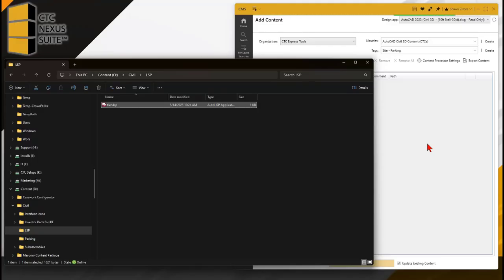So that saves a lot of the heavy lifting that we do with our AutoCAD profiles, because most of that stuff is setting up for list routine running and CUI distribution, potentially tool palette distribution, you know, all that stuff. I don't have to distribute really most of that because I can put the vast majority of that content directly into the CMS.